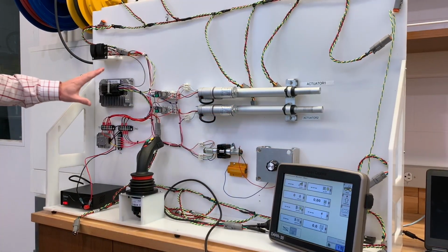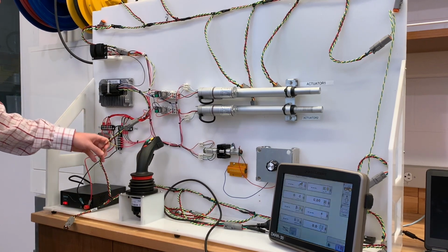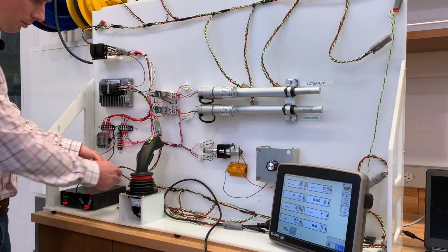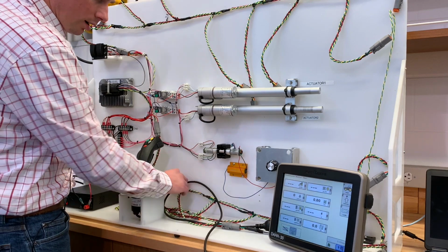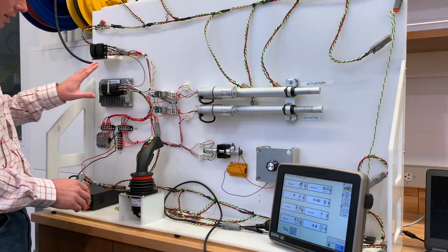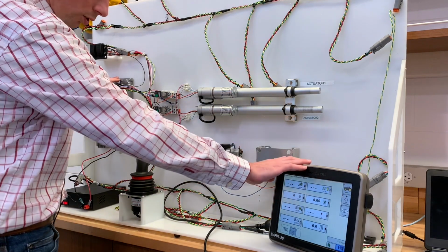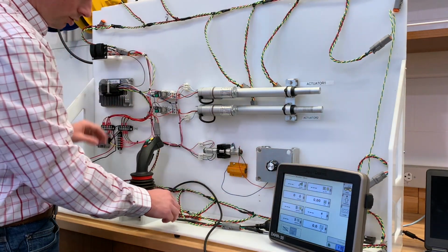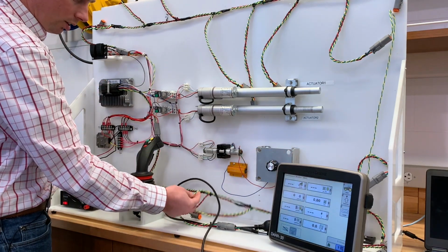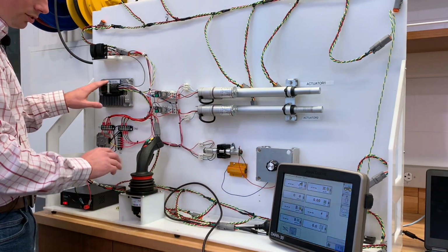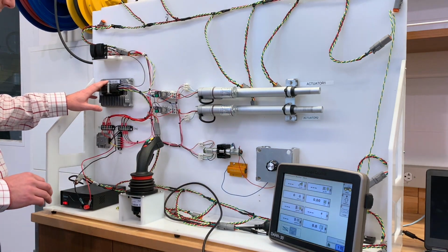All right, so just a quick background on this board, what we're seeing here. Number one, there are two CAN buses on here. There's a bus down here, the twisted yellow and green pair, and this runs across the bottom. That ties this controller and this controller together. When I say controllers, the only thing that really connects these three together is this yellow and green pair. So that allows communication between these three just through those two wires as part of the CAN bus.